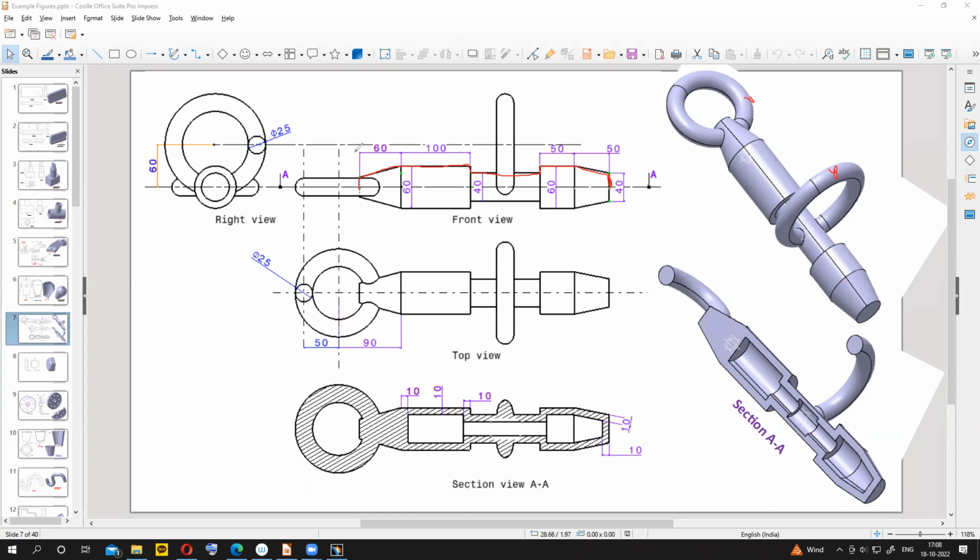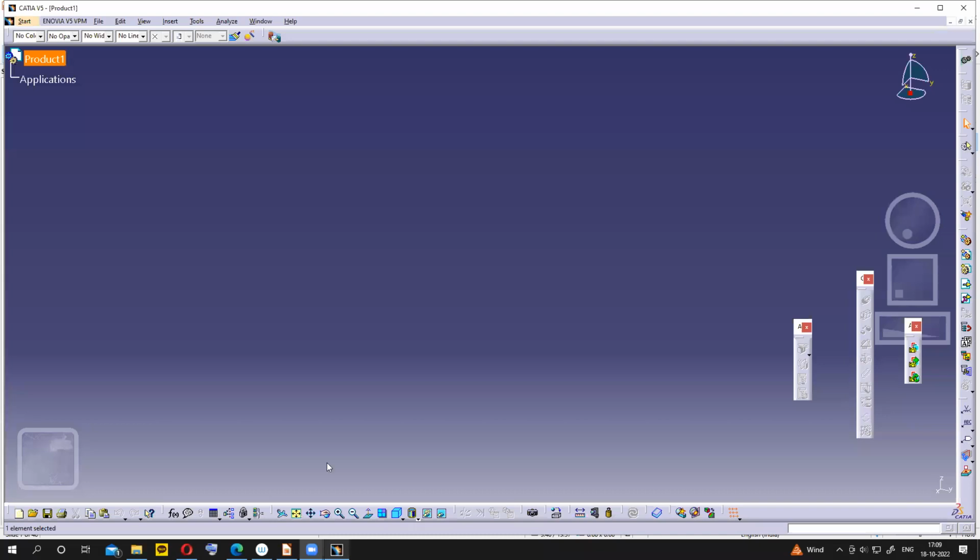You have to make the sketch on the YZ plane. Here you should not make these lines, because they are so sharp. If you make these lines, it's not a closed sketch, closed about the axis. About the axis we have only one closing point here and another closing point. So let's start making that one.